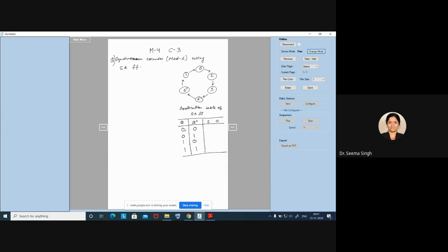And if I want to keep my next state as 0, this can also be taken as resetting of the flip-flop, and resetting output as 0 means resetting. So for resetting, the input of S and R is 0 and 1, correct? So 0 and 1 input of SR flip-flop will make it reset to 0, one possibility.